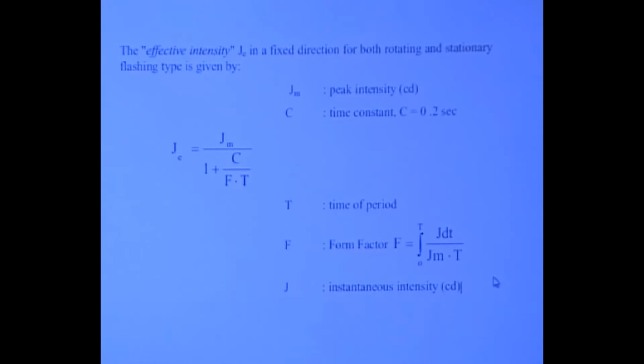So they did some tests, and they worked out that a flashing light, or a moving object, however you want to describe it, your brain is 5 times more likely to pick that up than a steady one. And that's what this 0.2 is here. 1 over 0.2 is 5. So that's effectively multiplying this by 5 to say you don't need as much light, because the fact that it's flashing gives you the warning. So that's what we're trying to solve.